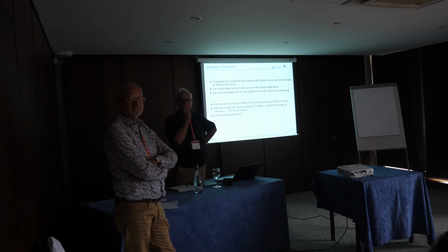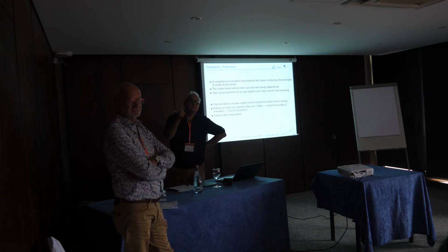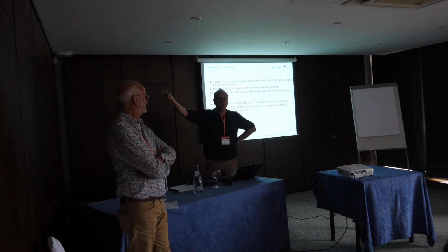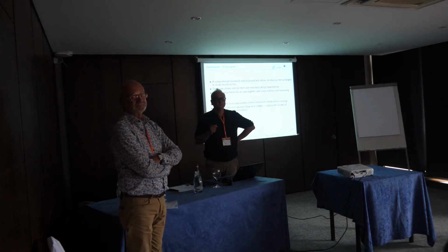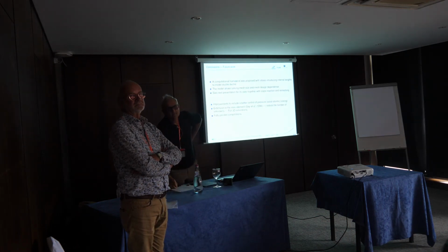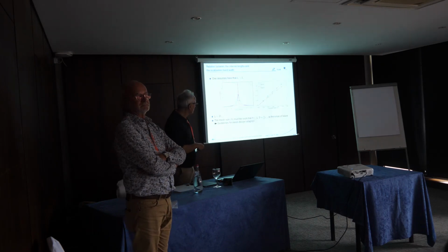Okay, and now I have my actual question. You have shown these different cases where you have this cup-cone behavior. What happens if you simulate a CT specimen? So Amar will show an example, but what do you expect? With the parameters I'm using, there is in fact no nucleation, it's just void growth, because it's high triaxiality. Sometimes I expect something like the crack starts to tilt. Yeah, but you need very long crack propagation. But you're completely right.